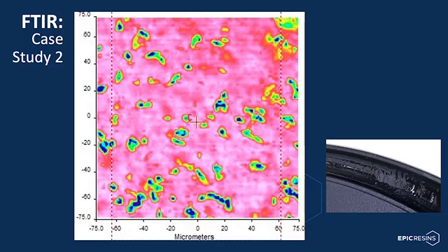In looking back at the FTIR array, the dots that are blue in the array are areas where the B side was not sufficiently mixed, and the pink regions are areas where sufficient mix was achieved. Upon sharing these results with the customer, they investigated their meter mix and dispense equipment and found that they had a partially plugged dispense head manifold, which was causing a lead lag condition during the dispensing shot. After completing necessary maintenance protocol to their equipment, we were able to re-verify their mixing process was correct.